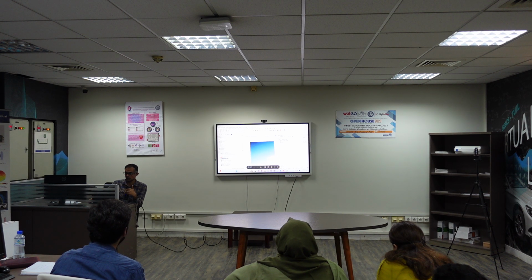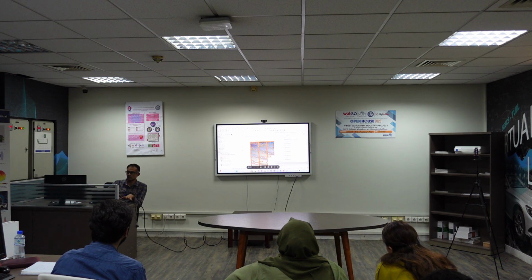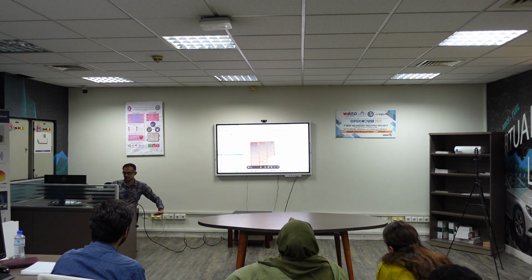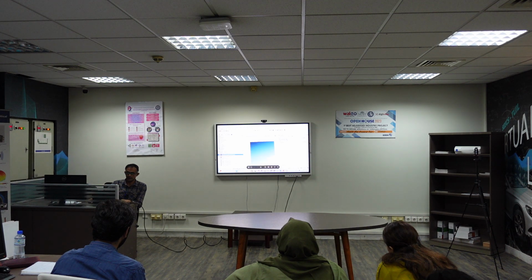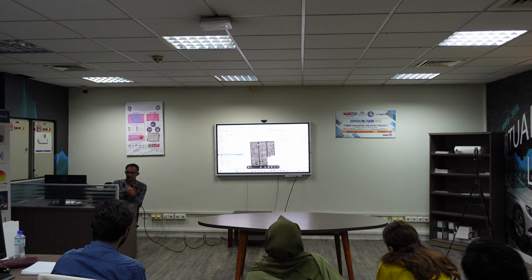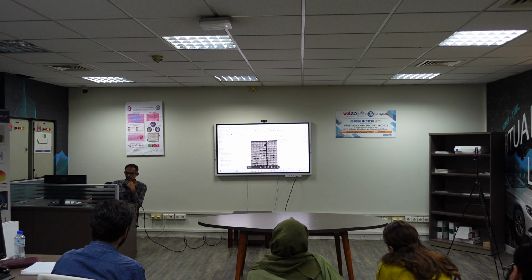using just interpolation, because each of these points has information of the height of that particular surface. If I interpolate all these points on that surface, I am going to get the digital terrain model of that complete surface. Now I have this complete terrain of that surface. Now all I am required to do is just subtract this digital surface model from this digital terrain model. Ultimately, I will get this digital height point, which will be the height of individual plots.